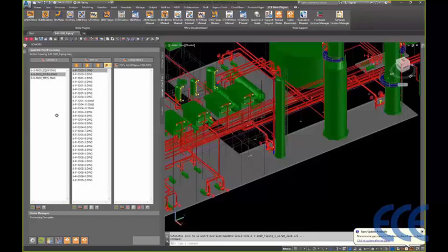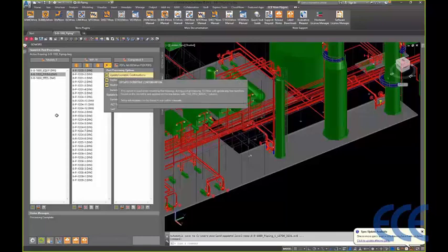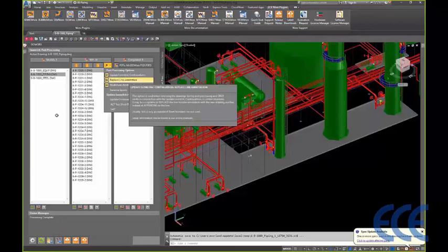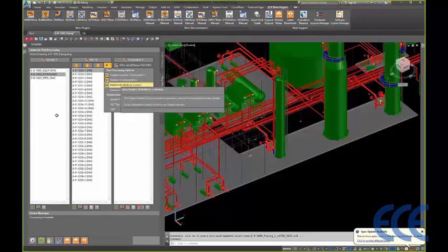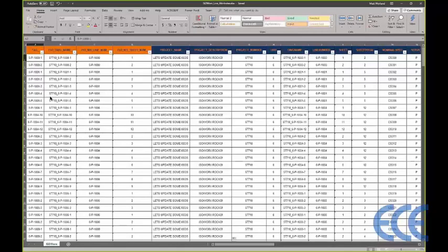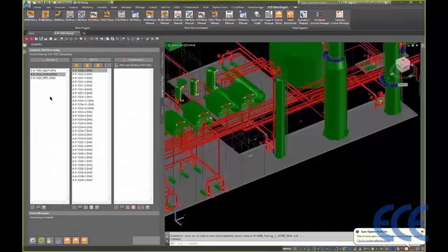And then we do give you a few more options in this little toolbox here. You hit the drop-down list. If you are going to be updating the name to include the ISO DWG column, you might want to use this turned on right here. It'll update the continuations to also show the new field. If you're using number 2 and you want to replace the information, then maybe you want to go through and replace the annotation as well inside your ISOs. And then finally, number 3 is the multi-sheet attribute control. And that's where I talked a little bit earlier about if you have these 1, 2, all the way down to 12, or however many ISOs you have individualized, you want to make sure you turn that on, and that will allow the software to process each line individually.